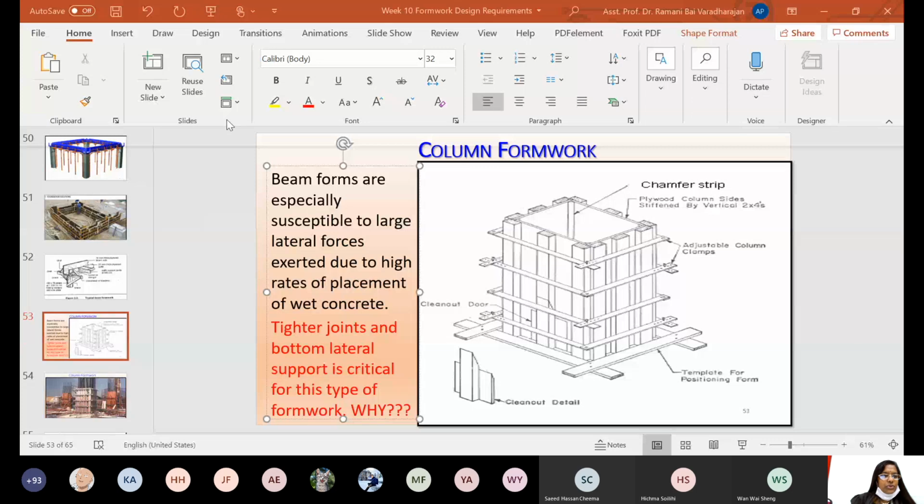There are different component parts shown here. I will explain one. You can go through others yourself. But different types. Let's see one. Opening for a beam. This is the opening with all the reinforcement inside, right? And then this is located around the kicker, right? Around the kicker. Fillet to form the chamfer, right? Fillet means just an offset, a kind of offset is provided for the formwork, for the concreting. Margin piece, right? And then the formwork panel of boards or sheets or material.